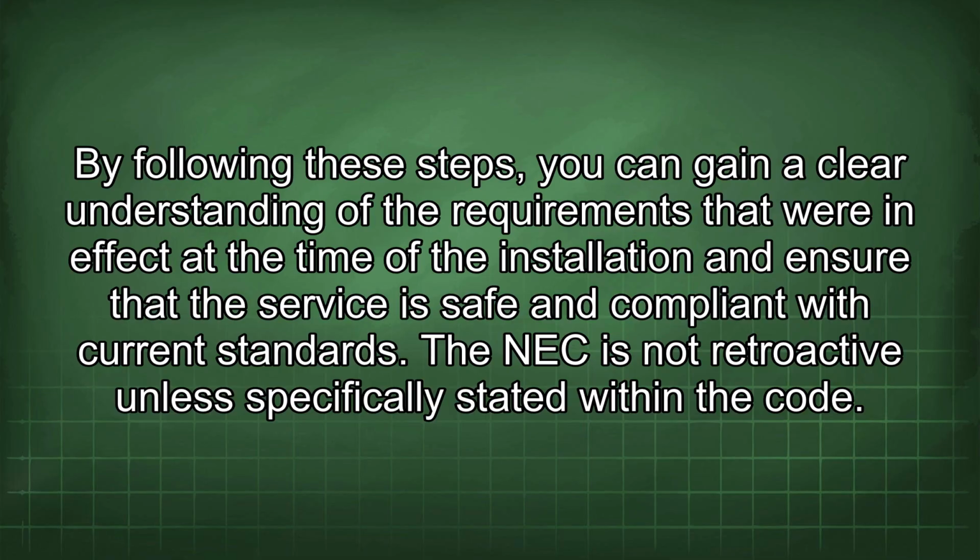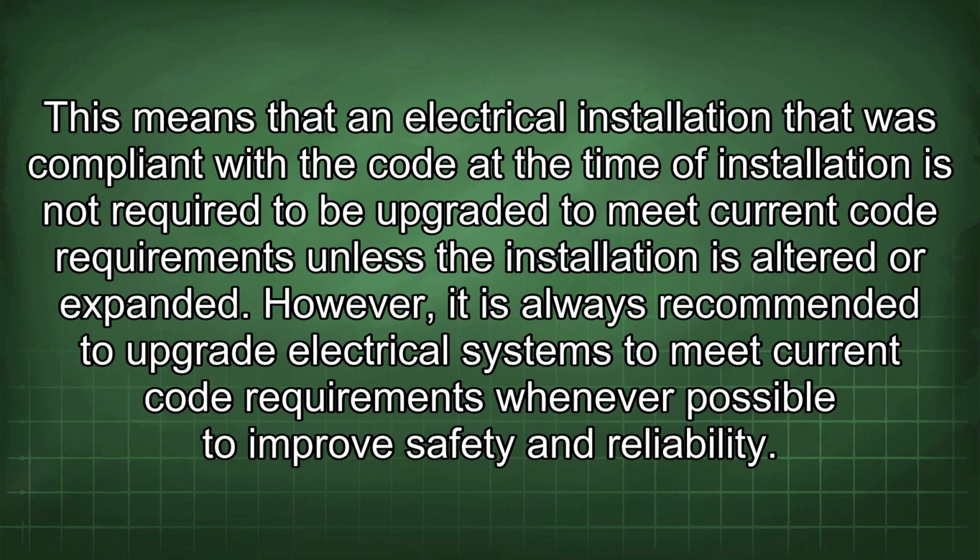The NEC is not retroactive unless specifically stated within the code. This means that an electrical installation that was compliant with the code at the time of installation is not required to be upgraded to meet current code requirements unless the installation is altered or expanded. However, it is always recommended to upgrade electrical systems to meet current code requirements whenever possible to improve safety and